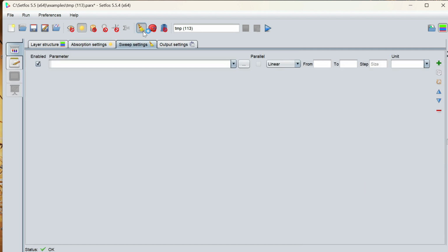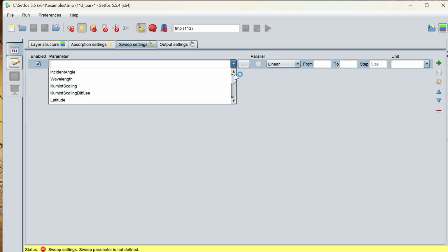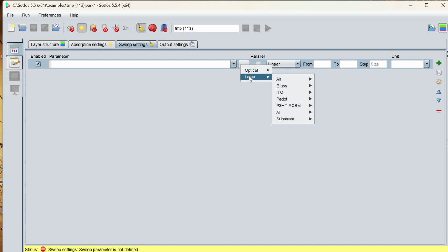When we activate the sweeping mode here, when sweeping over the parameter date and time, set to compute for each sweep point the time and location dependent incident sun spectrum, run a simulation for the corresponding light incident angle, and post-process the sweep points to obtain the overall energy generated by the solar cell over the time steps.